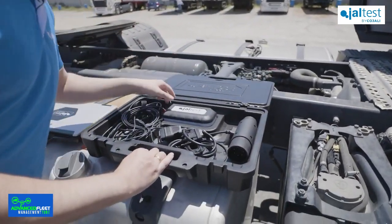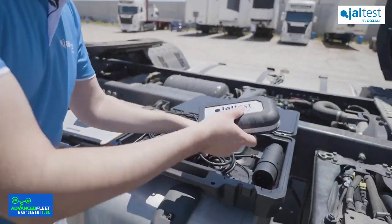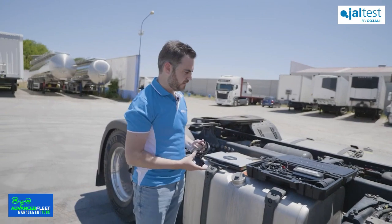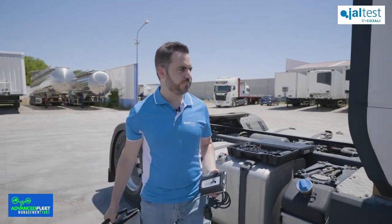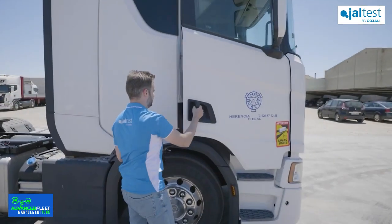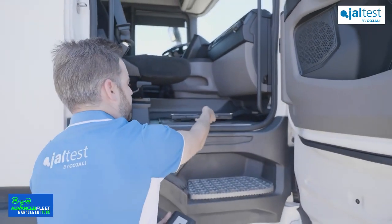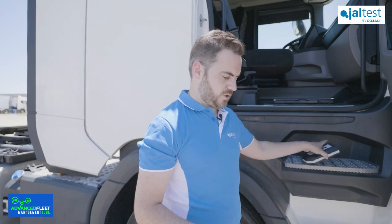For that, we will use our vehicle communication interface, the Jaltest Link V9, the OBD2 connector, and our laptop with the latest Jaltest version installed. As we will use Bluetooth mode, we don't need anything more. On this side, you will find the OBD2 connector. Remember that Jaltest software will guide you in all the diagnostic repair process, so all the locations and for sure wiring diagrams and more information will be provided by the software.